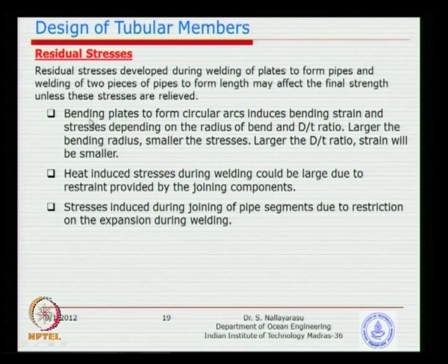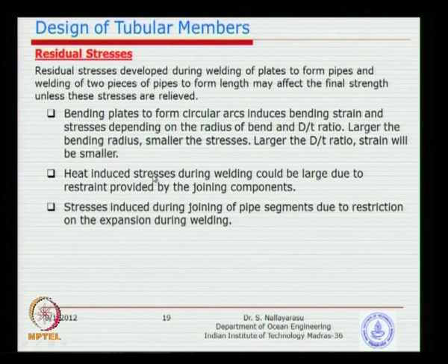There are three forms. First, bending plates: you take a flat plate and bend it, which is simple beam bending theory. You can calculate what the stress could be. If you take a 2-meter plate and bend it to a required radius, you can find out the stress. Second, heat induced stresses, basically a temperature effect. I think most of you have studied the thermal coefficient of steel and the expansion related to length and thickness. As long as the expansion is allowed, no stresses will be built. If the expansion is not allowed, corresponding axial force or bending force will come. You can find out depending on the size and the flexibility allowed.